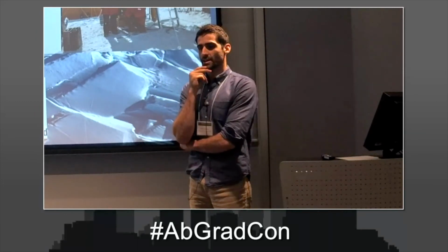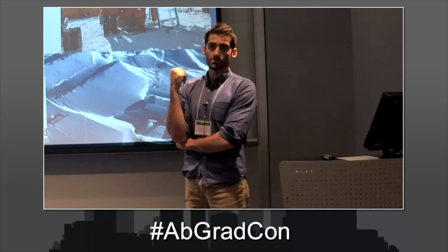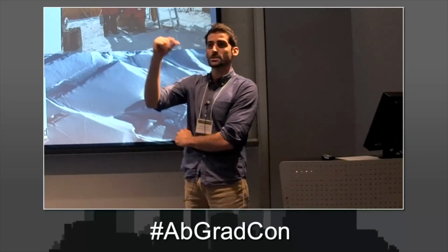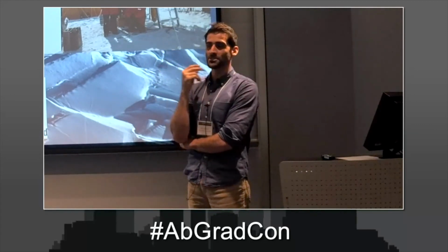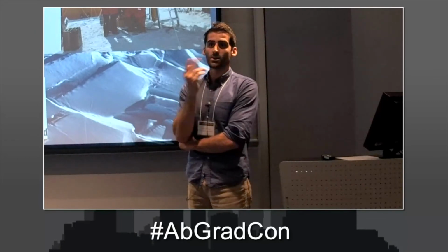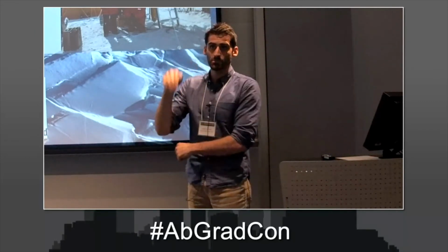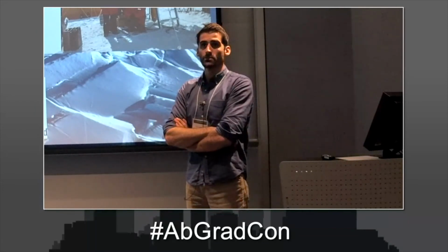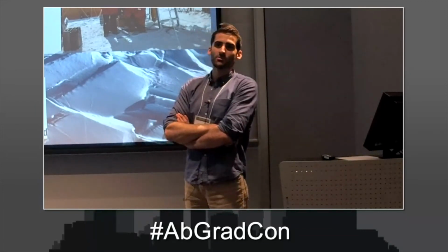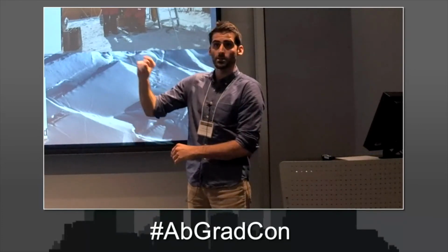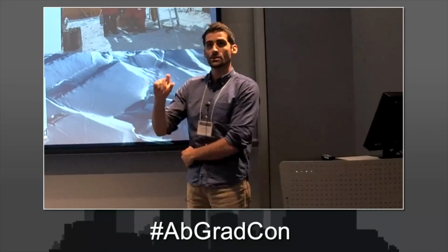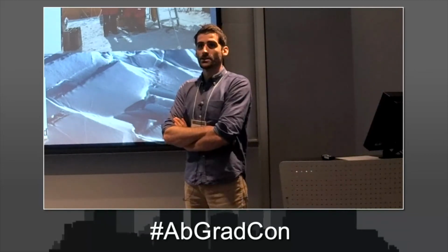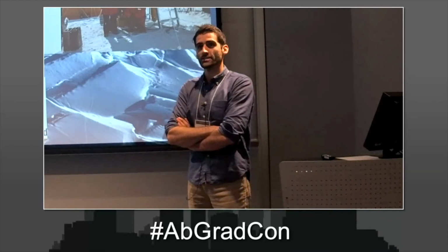One of the technologies that we actually use for localizing the robot underwater, because you can't use GPS, GPS only makes it this far through water or ice, not great for the depths we're trying to go to, is acoustic and long baseline transponders that you basically ping and use that to triangulate. So yeah, I think acoustic technology will really be the way forward. There's talk of a robot that melts the ice shelf and drops off little pucks behind it every couple kilometers that are acoustic modems and amplifiers to get data back. Because it'll be a one-way trip for the robot whenever you go to an ocean world, but you need the data back. That's a good question, thank you.